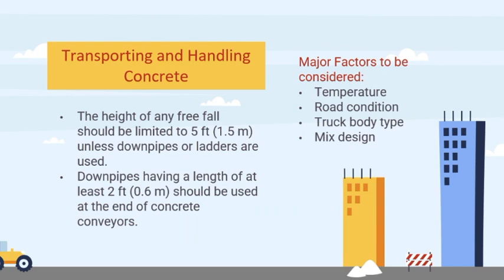So go back. And of course, there are major factors to be considered for the maximum safe hauling distance for transporting concrete. The major factors to be considered are temperature, road condition, truck body type, and mix design.